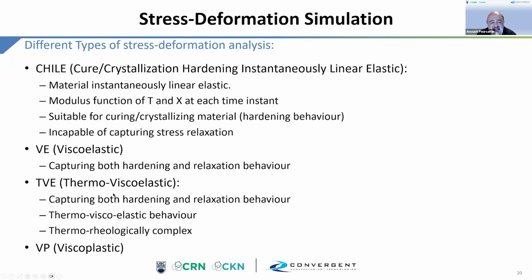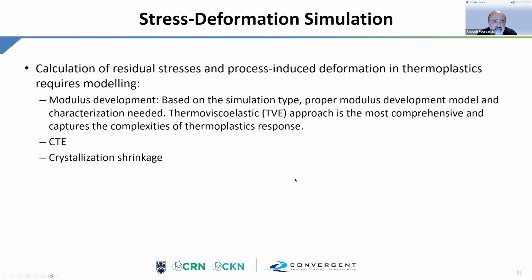We characterize the material at the full thermoviscoelastic level, but often we actually exercise it by simplifying the use of the material model at the child level for this very simple reason that running a full thermoviscoelastic model is computationally very expensive and quite sensitive. It needs a lot of love and care to get it to run fully.